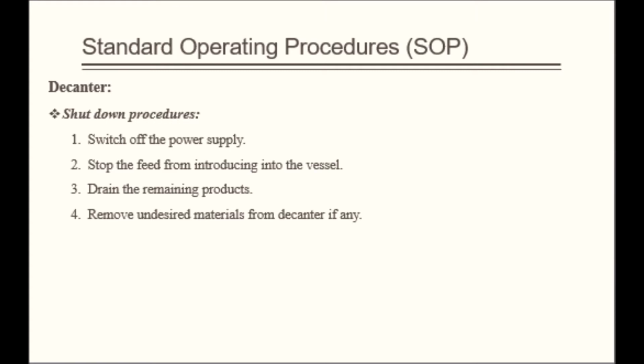On the other hand, when shutting down the decanter, we have to stop the feed from entering the vessel, then drain the remaining products. Lastly, remove undesired material from the decanter if any.